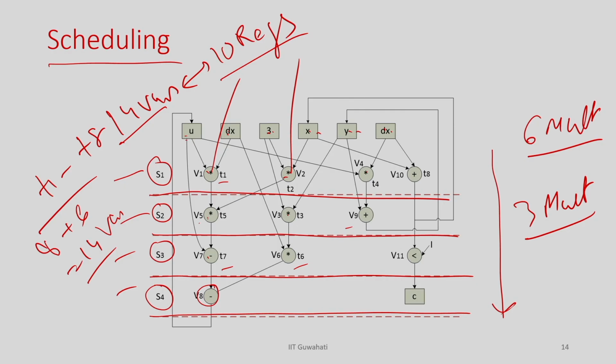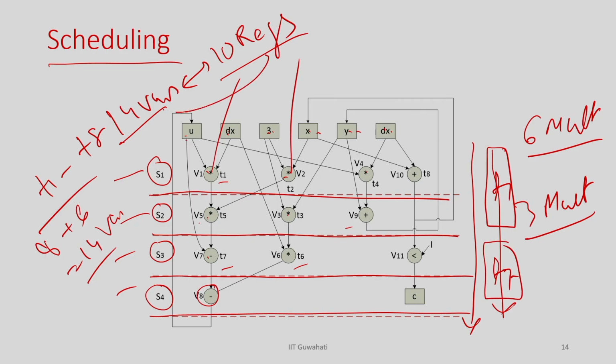variable. So, that means for some time stamp it is going to store one variable and at another time stamp it is going to store another variable. For example, here there are 4 time stamps, so there are 4 clocks; maybe one register is needed to store T1 for this time and say T7 here. Then only it is possible. So, that is the problem: given this schedule, how do you identify the minimum registers and their binding. Okay, that is something let us understand.